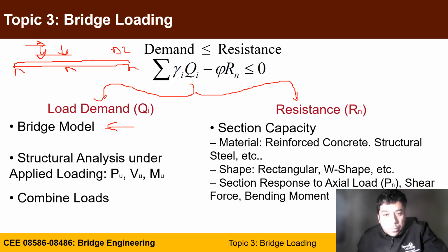So you need to come up with your structural analysis under the applied load, be it dead load or live load, to get your ultimate axial loading, ultimate shear loading, and ultimate moment loading. And you have to do it for each type of loading that you are expecting on this bridge and combine them with different loading factors to get your demand side, which is summation of load factors times your loading.